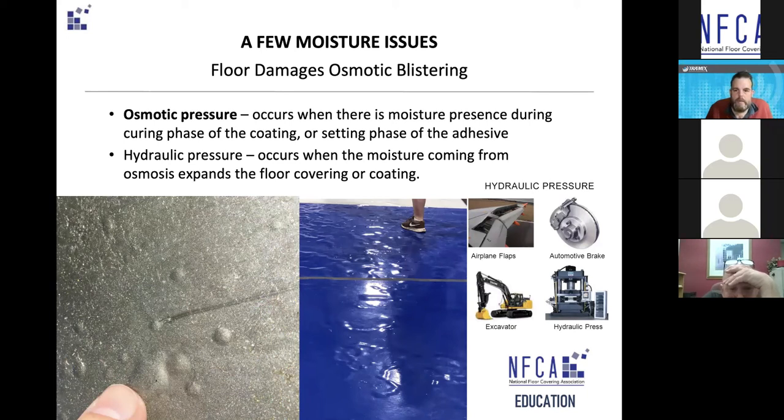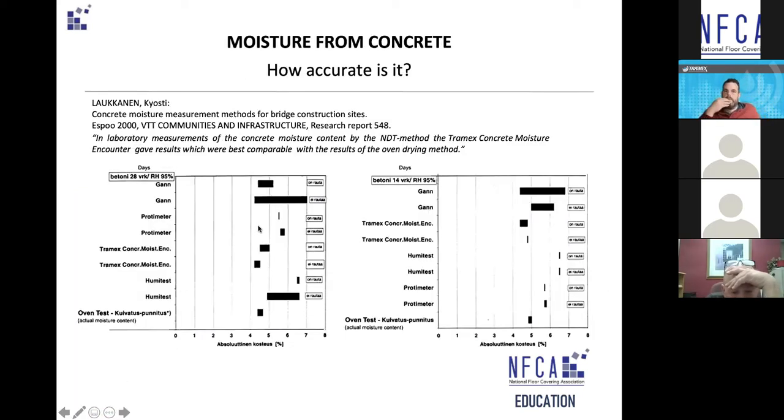The solution is to make sure that the surface of the concrete is dry enough so that the curing or the setting, depending on whether it's an adhesive or an epoxy, can take place without creating a byproduct. And that's where fans are often used. I'm just going to go on to this part, because there'll be a lot of questions from this. I can see from Bob's chat and others that there'll be a good bit of discussion. So I'll just quickly go through this.